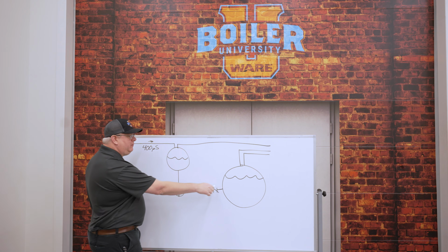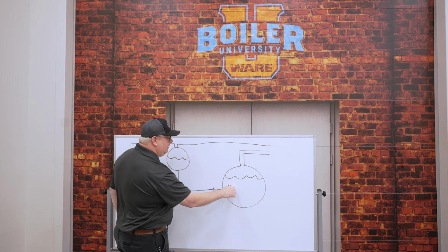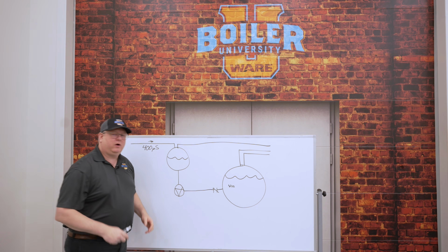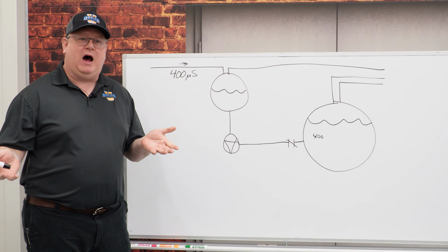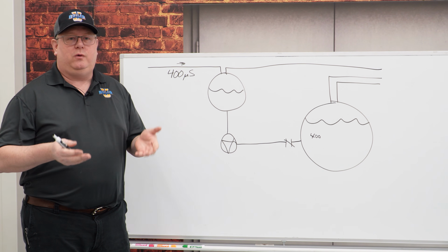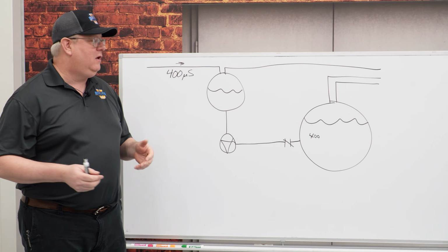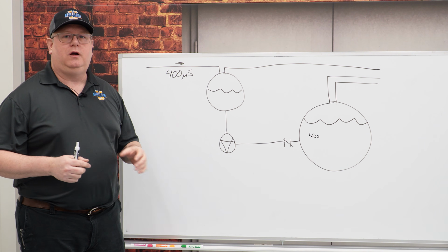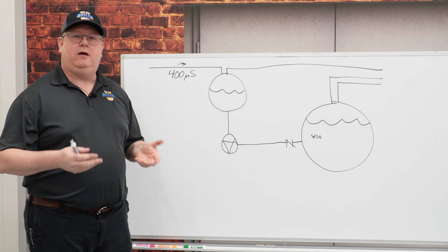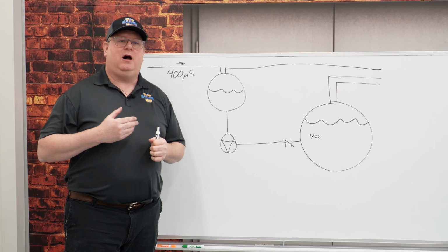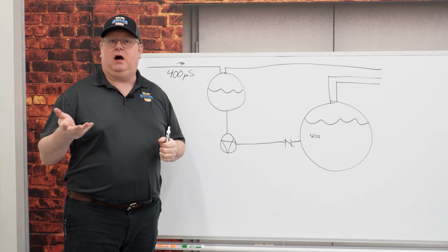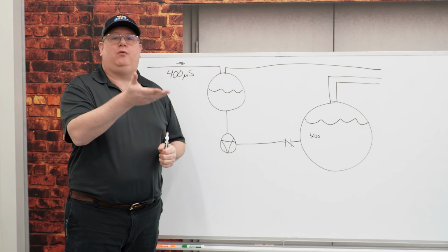That water is pumped into the boiler. So when we initially fill a boiler, we're going to have that 400 microsiemens of conductivity. Is that too high? Is it too low? Well, we really can't get any lower than that with this feed water, and it is on the low end. What's the issue with low conductivity? Nothing initially. It's just that we expect it to rise.